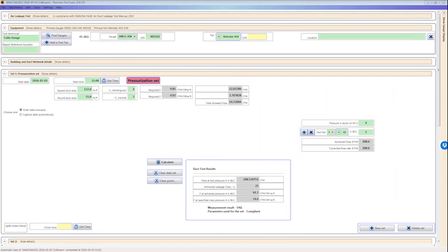Blower doors run out of steam at around 100 pascals, 0.4 inches of water. Anything over that, they start to get extremely inaccurate. So you can't even get a measurement at 1 inch of water; it's the wrong kind of blower. It's designed to blow a lot of air at low pressure, and here we're blowing very little air at high pressure. So it's the exact opposite. These are like Formula One cars, and blower doors are more like gravel trucks. They move huge volumes of air.